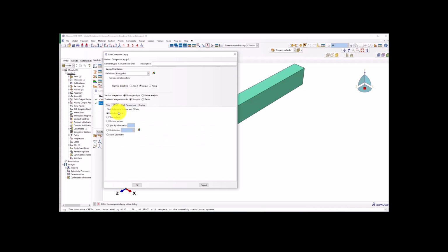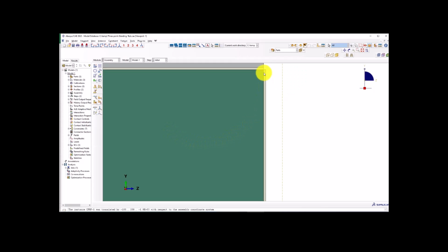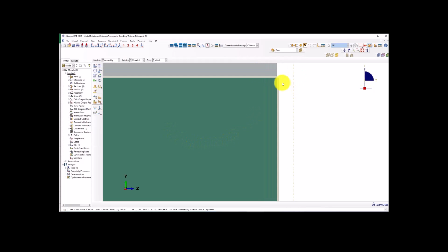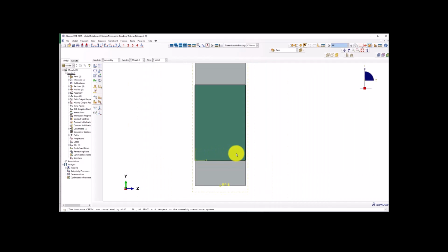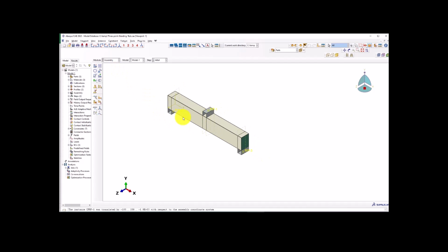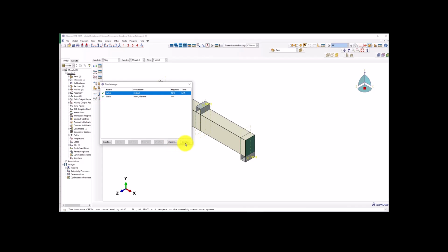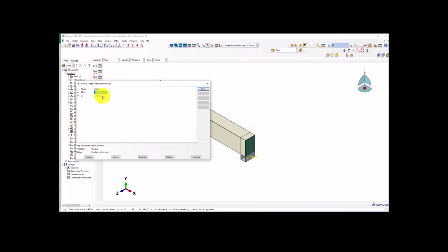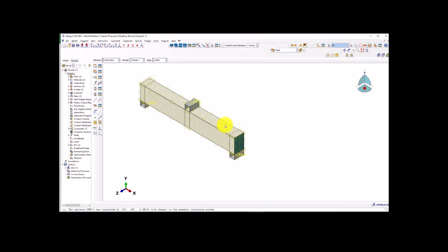So both are using the offset bottom surface. Now we go back to the assembly and let's see it's changed from inside to outside. In both areas it's showing outside. So now properly we construct both elements together. Next, the assembly is finished, the step is already given, we created two steps and two step outputs. You can check in the previous video, I have given a complete explanation, and here is the interaction.